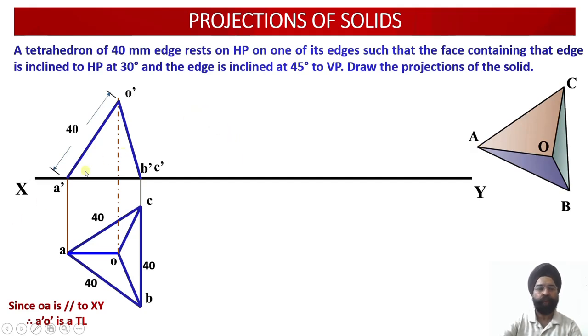So now I am going to transfer this triangular figure, that is the front view of elevation, over here such that the base angle, means angle of A1 dash, B1 dash and C1 dash surface with respect to HP, should be 30 degree. So please see, now I have transferred this. Now once again, rectilinear distances we can use to transfer this. How? Mark this point as point 1. This will be my point 2.